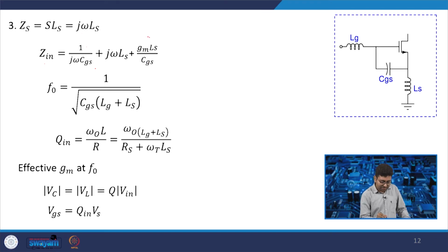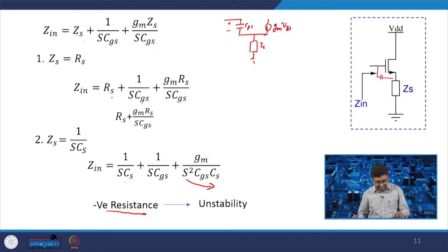So, here this term itself is resistive. In the previous place, we also got a resistive term, but again this resistance will add noise, that we have already seen in the previous 2-3 configurations, that we want to avoid the resistance and we want to get the input impedance 50 ohm.